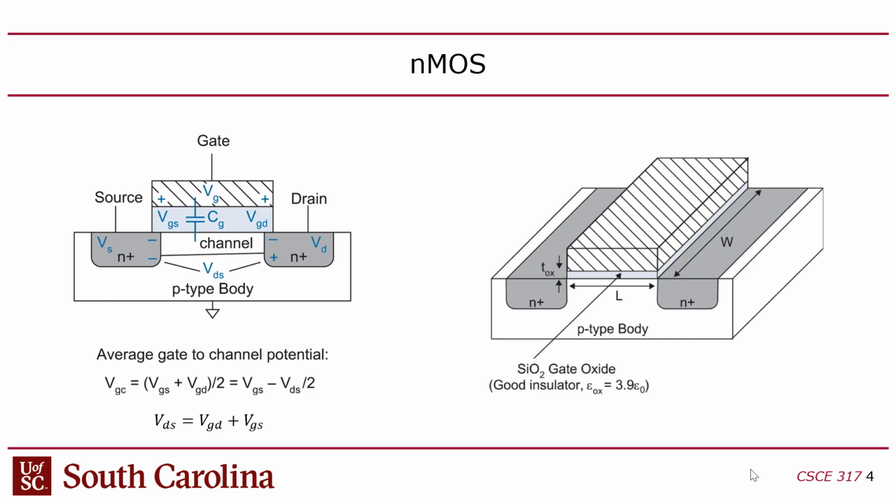And so those transistors will typically have a wider than minimal width, but the length will still be minimal, whether it's 130 nanometers, 90 nanometers, 45 nanometers, whatever your fabrication process is. You guys with me? So you want the length to be minimized. The width can be minimized if you want the smallest transistors possible, but if you want power, then you have to go wider.